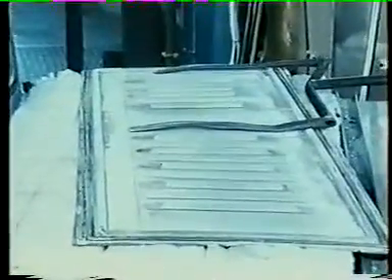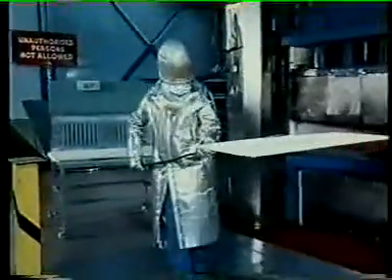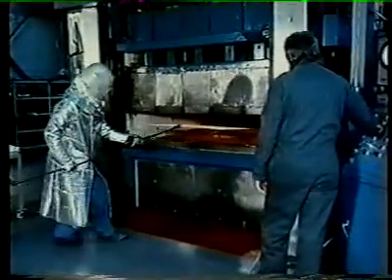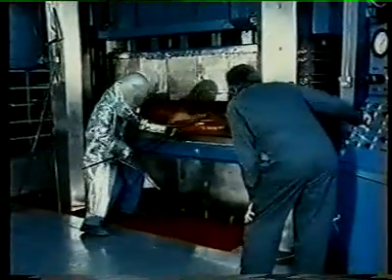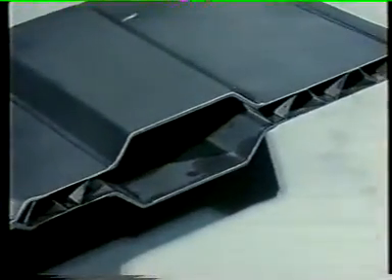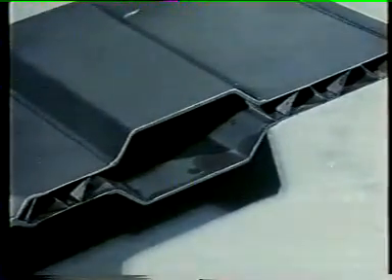New manufacturing techniques may also have an impact on design. This is superplastic formed titanium. Titanium is highly corrosion resistant, and the combination of this forming technique with the process of diffusion bonding reduces the number of fasteners needed, so cutting down the number of potential sites for galvanic corrosion.